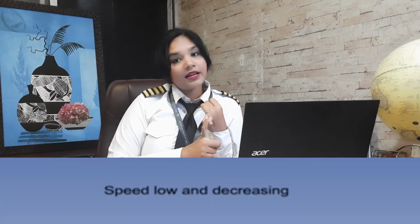Okay, so these are some of the factors affecting stalls. Now coming to certain signs of incipient stall, things you have to note before a stall happens. Incipient stall is when you're not completely stalling the aircraft, you're approaching stall. First, flight controls are less effective.